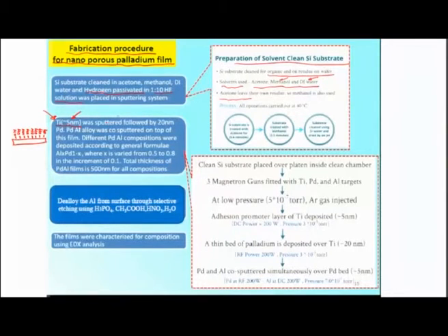The 5 nanometer layer is followed by another layer of 20 nanometers, and this is pure palladium, which is actually the sensing element. We all know that palladium changes resistance because of the formation of palladium hydride at the grain boundaries, and also a change of state from the alpha to the beta state of the palladium. And essentially after this 25 nanometer film, with the hydrogen passivation, the next step is a 5 nanometer titanium layer, followed by another, slightly thicker, 20 nanometer palladium layer. So this is titanium, and this is palladium coated on top of the titanium.